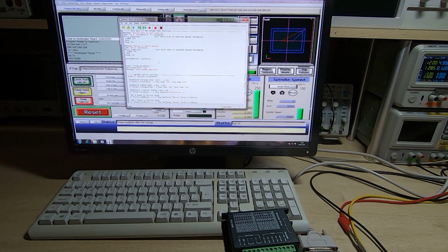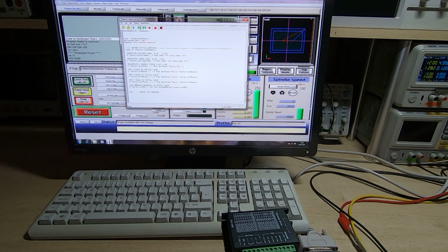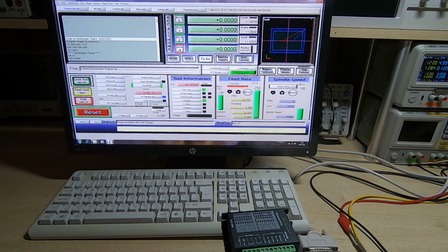That's the selected tool within MACH3, and then it restores some of the status values for the machine, because again, remember, we're part way through a milling operation here, so we've got to make sure that we restore anything that the G code may have modified. Otherwise it could disrupt and cause chaos when the machine tries to continue milling. And once it's done that, this macro ends, and the machine then continues with the milling operation with the new tool in the correct Z position, and the X and Y restored to what they were before we changed the tool.